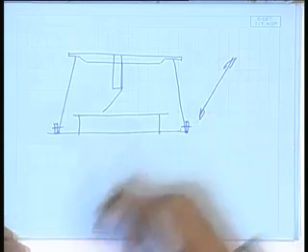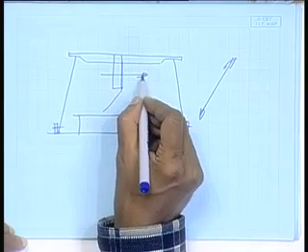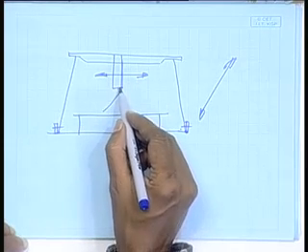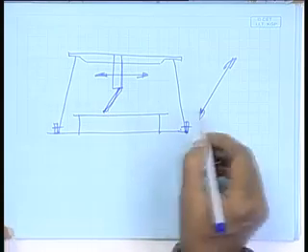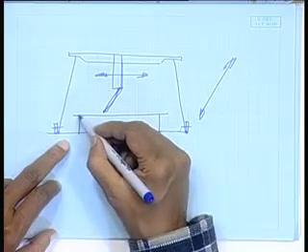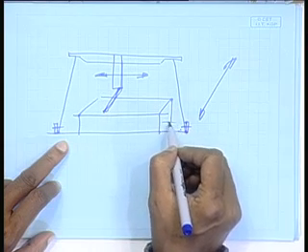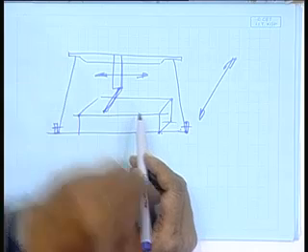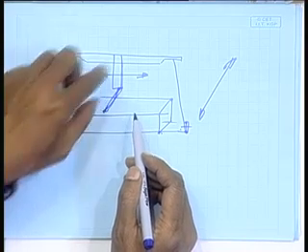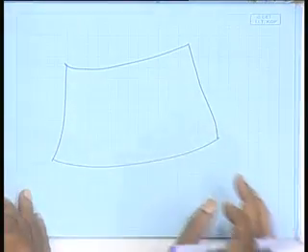This whole gantry is moving on wheels along this axis, and the torch can move along this axis. Say this is my cutting torch, so it can cover this entire square space, the cutting table. Over this table it can move. In the same way, in this gantry I hang a heating torch which can move in whatever direction you describe. It will go on moving and go on heating, and thereby I can generate the shape.